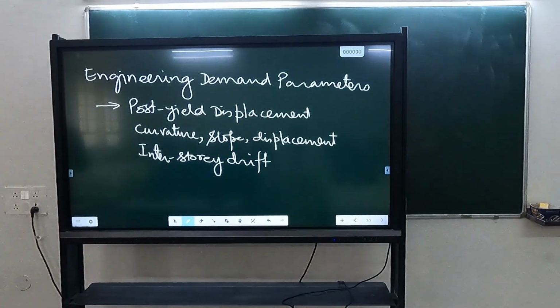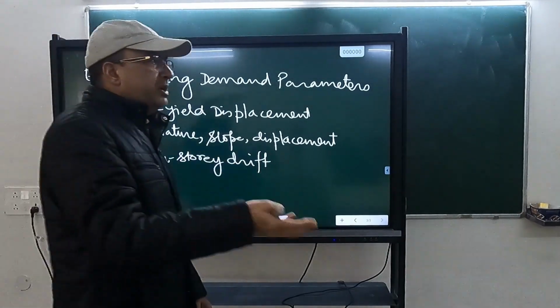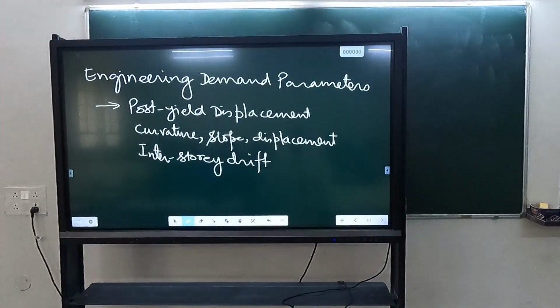There are masonry walls. So the masonry walls in load bearing structures will be called load bearing walls. Infills we call only when we are putting these masonry walls in a frame. Then these will be called infills. So if it is a masonry building, then the walls themselves are the structural elements. There are no columns. So those walls themselves are actually the structural elements.